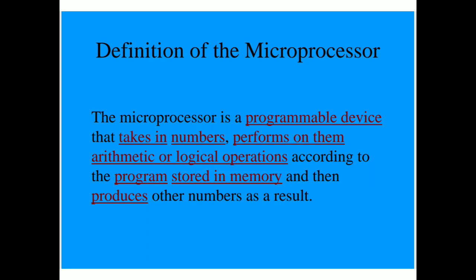A group of 8 bits was referred to as a half word or byte. A group of 4 bits is called a nibble. Also, 32-bit groups were given the name long word. Today, all processors manipulate at least 32 bits at a time, and there exist microprocessors that can process 64, 80, 128 bits.